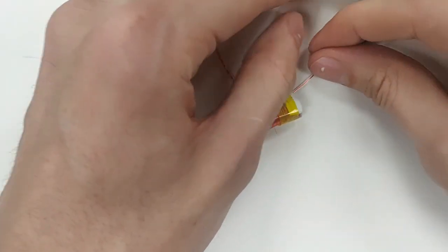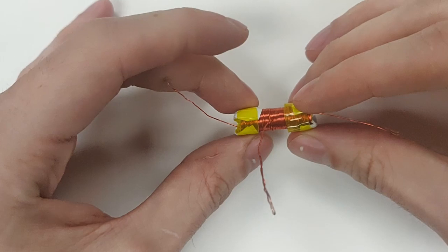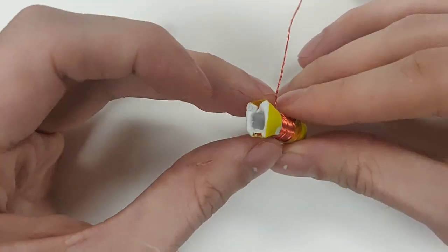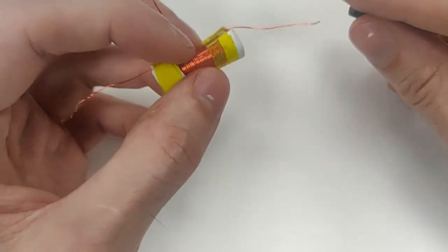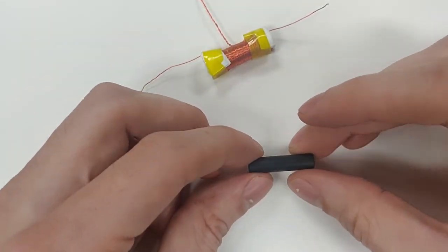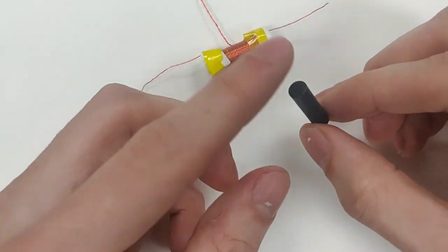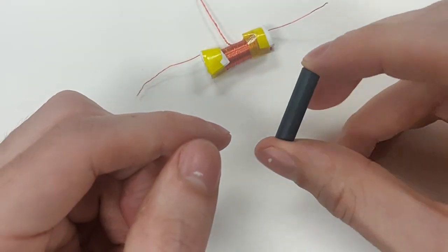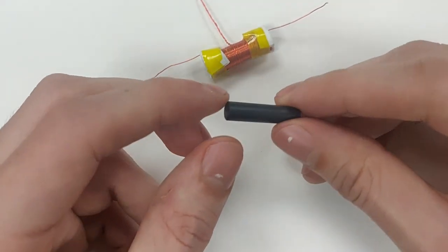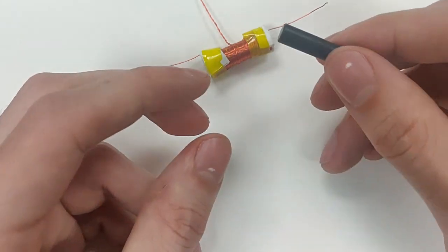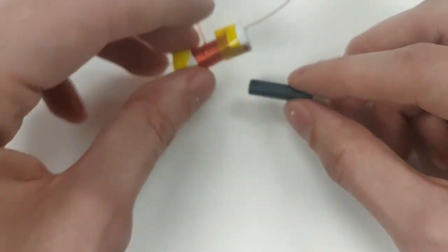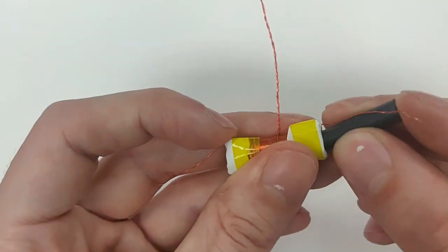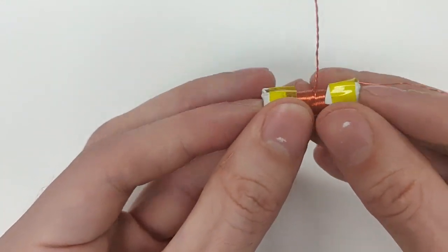So first part is creating this solenoid, and it's fairly simple. We start off, if we follow along in the lab manual, with a ferrite core. And that's just because it has a high permeability. We wrapped that ferrite core in paper, as you can see here, and that's just so that we can easily slide it in and out of our coil.